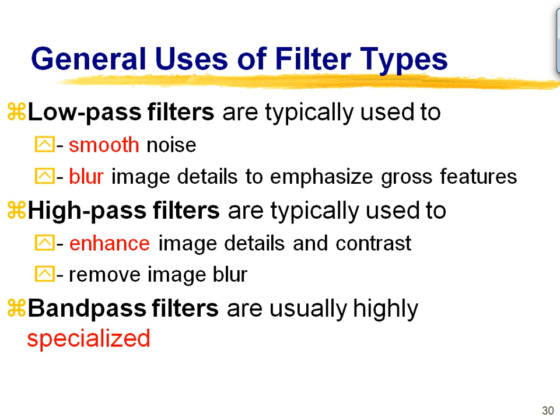But of course, if there is noise in the image, it will bring out all the noise, right? Actually, it's not that it's bringing out the noise; the noise becomes much more prominent because we are retaining all the noise but removing the low frequencies. So smooth things go away and the spikes remain. Okay? The image starts looking very noisy.